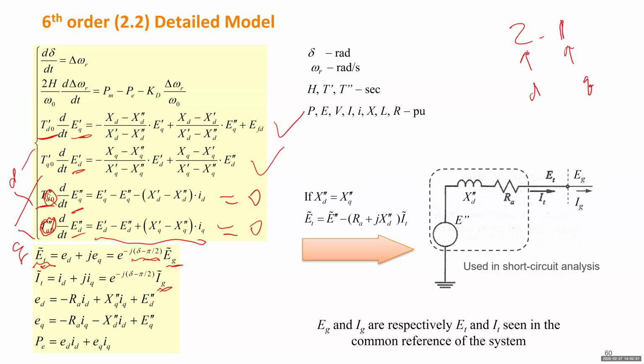But when you connect all the generators together through the power flow equations, the voltage and current in the power flow equations need to be EG and IG, with the angle shifted by that little angle. Otherwise, your calculation won't be correct.